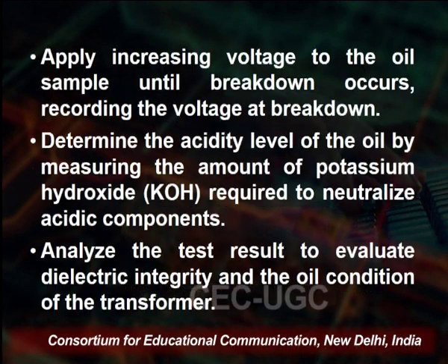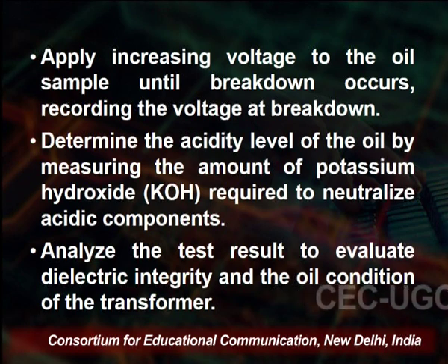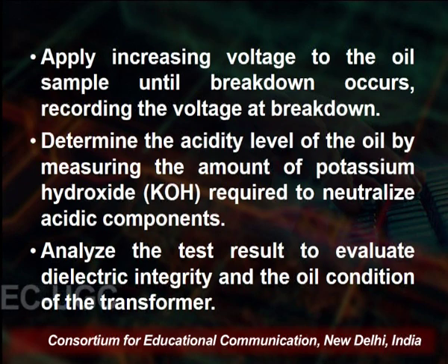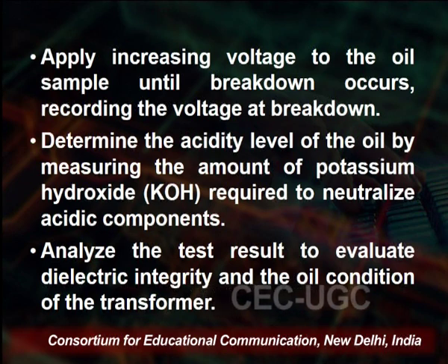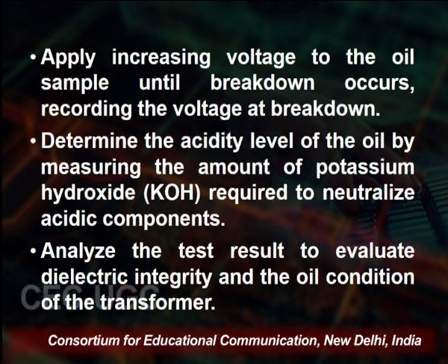After that, apply an increasing voltage to the oil sample until breakdown occurs, recording the voltage at the breakdown, meaning at what voltage the breakdown occurs will be measured. After that, determine the acidity level of the oil by measuring the amount of potassium hydroxide, that is KOH, required to neutralize the acidic components.